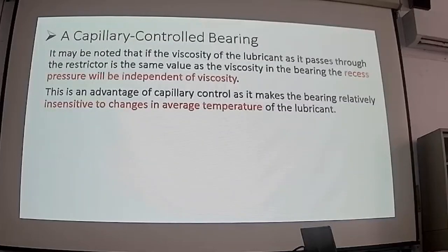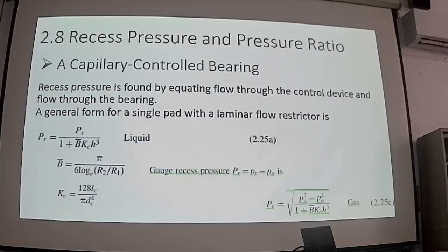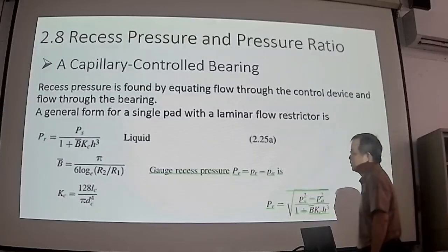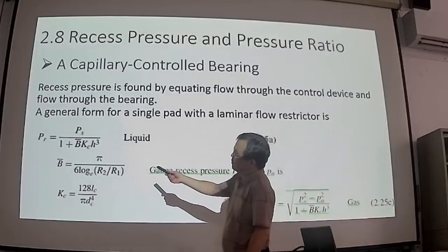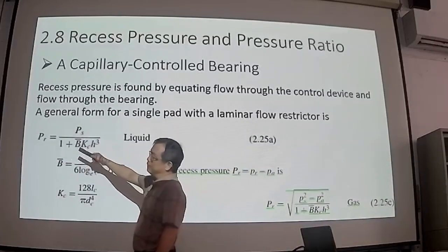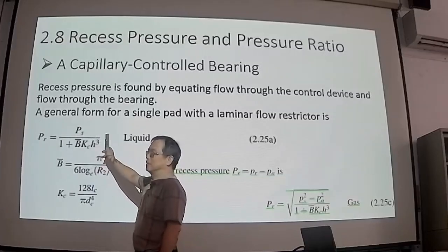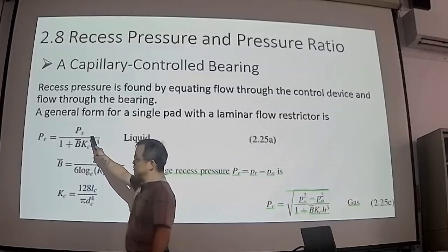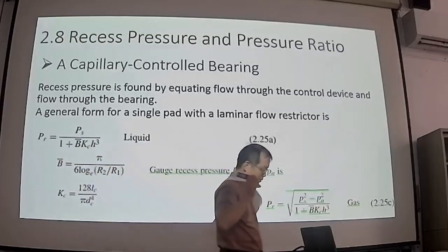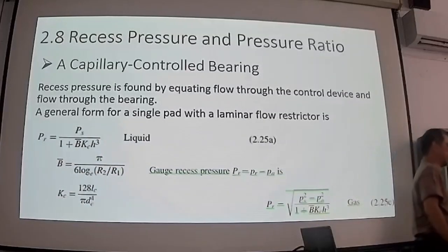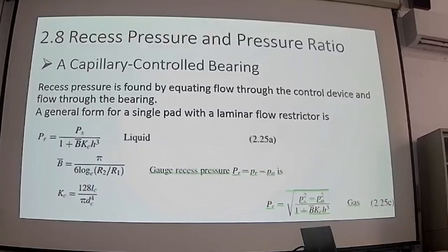In this case, from the formula, this is quite important, the conclusion on this page. In this relationship for PR, we don't have any viscosity inside the formula. So the capillary restrictor design is not sensitive to the temperature rise.